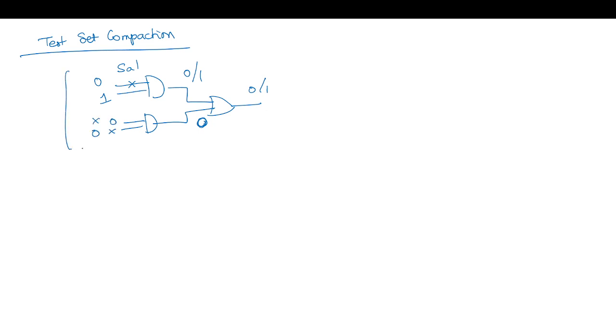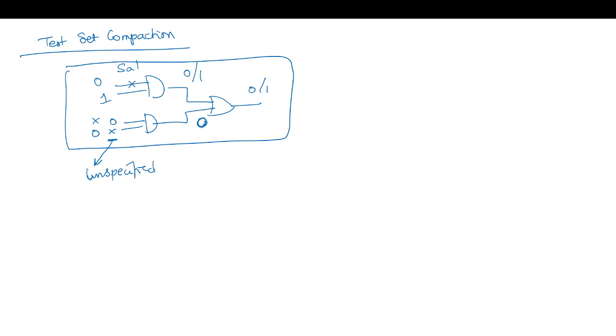So you can see for this simple circuit, that we have some vectors which are unspecified, or this pattern like 0 1 x 0 or 0 1 0 x. These are the incompletely specified patterns. Patterns, or you can say vectors. So some of the vectors can be compatible.